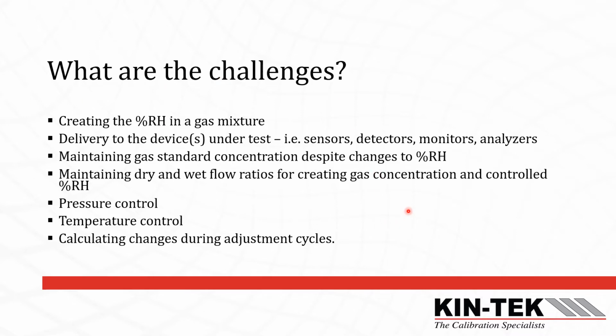So what are the challenges? Well, first we got the creation of the percent RH in a gas mixture. So we got to put that together and make sure that we're not losing the gas to the percent RH. We also have to deliver to our device under test, whether it be a sensor, detector, monitor, or analyzer. And we have to maintain the gas standard concentration despite any changes we do to the percent RH. So there's a lot going on there.